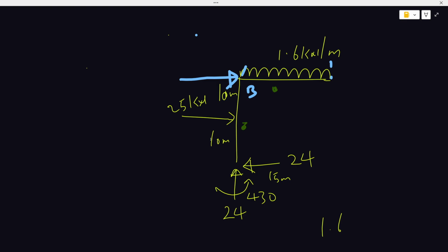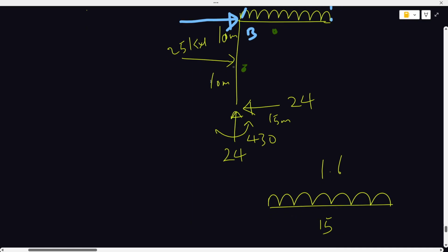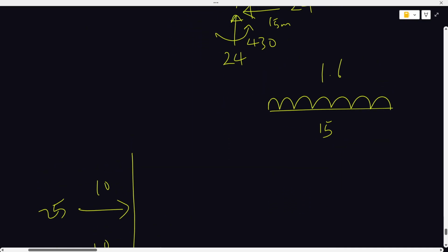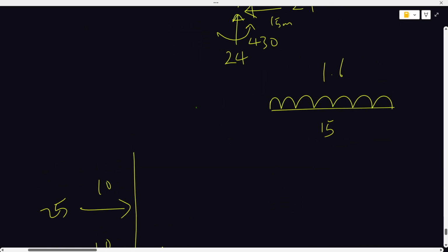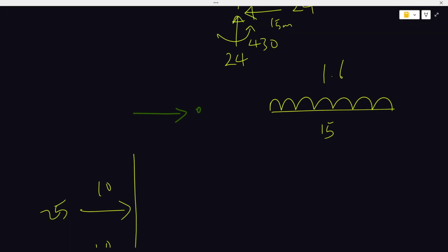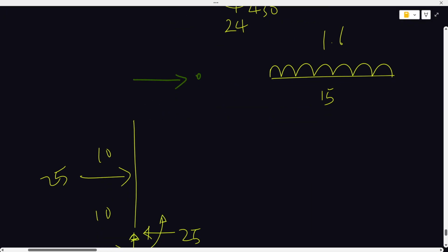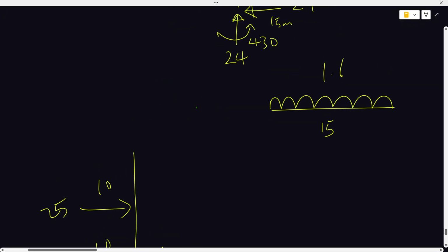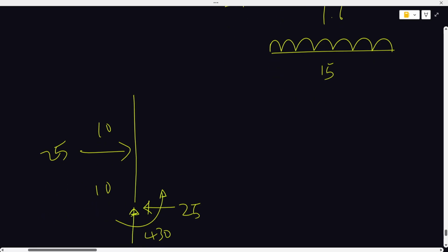Don't think of it like that, it will confuse you. To avoid that thought, just apply that force to the joint alone. Put the joint and apply that force, then draw the free body diagrams of all your members. But luckily for us, no force was applied on the joint, so we can proceed.